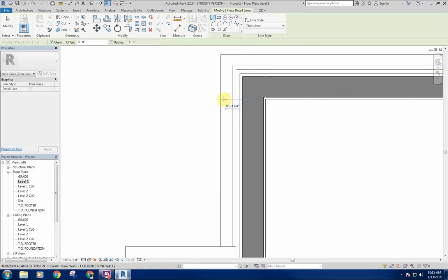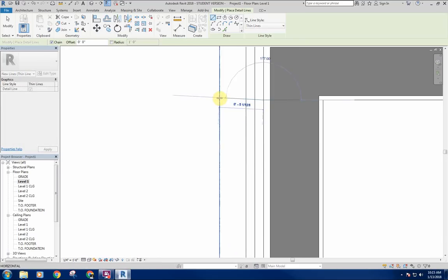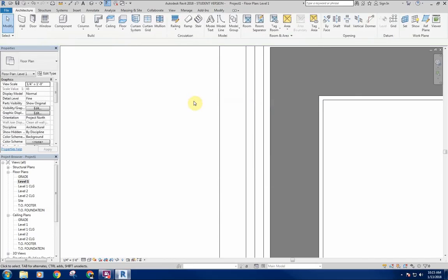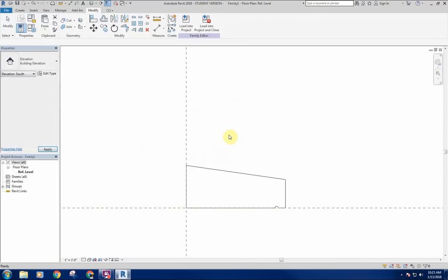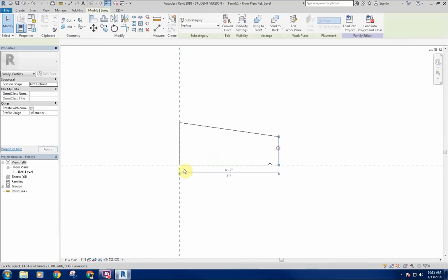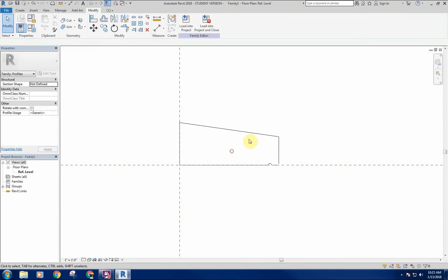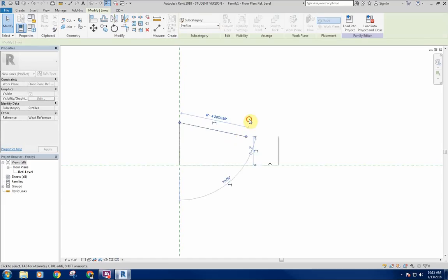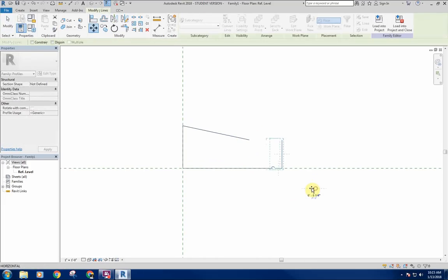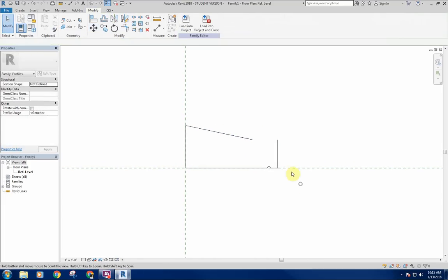I'm going to end up with a sill. So there's 5 inches. If I end up with, say, a 7, so 5, let's say it overhangs 1.5 inches. So that'll be a 6.5 inch sill. So I'll flip between all these views. Now I want this to be 6.5. So let's move this back 1/2 inch.